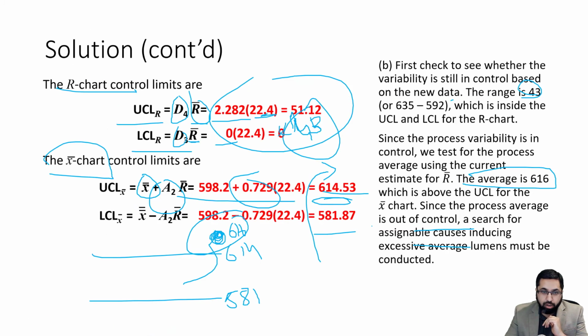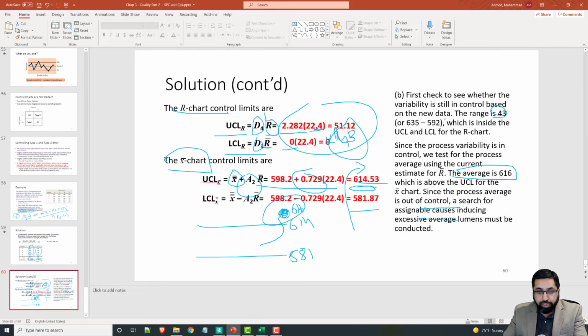So that is all for this lesson. What did we cover? We covered process variation, common cause and special cause variation. Then we talked about process capability. If a process is capable, it makes sense to control it. To control the process, we can use X bar R chart or P charts or C charts, right? And when do we use each of them? That is all.